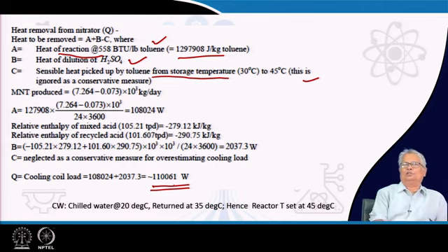You will notice one more thing also. Here what you require is a cooling to a temperature of close to 30 degrees centigrade. The conventional cooling tower which gives you cold cooling water at a temperature of around 35 degrees centigrade will not work well here. So, what you require is a chiller, and the chiller is expected to have a temperature of around 20 degrees centigrade chilled water for cooling available to you. If you wish, you can use the circulating system of chilled brine also. This is also quite common.